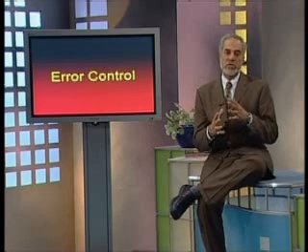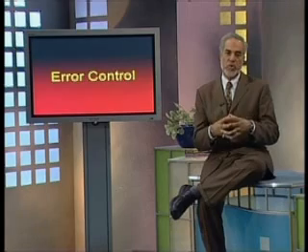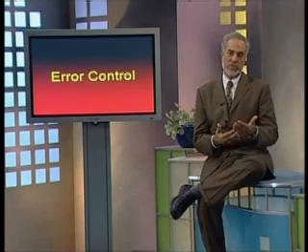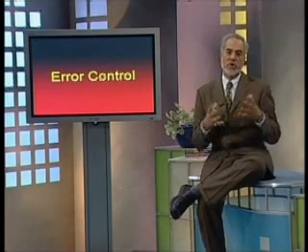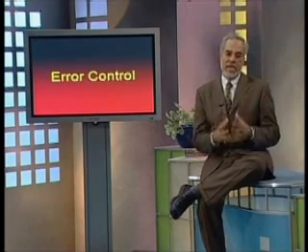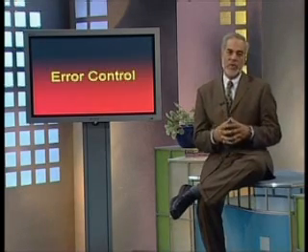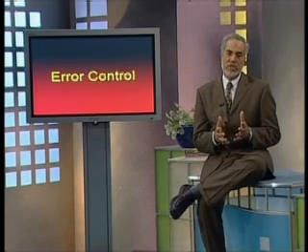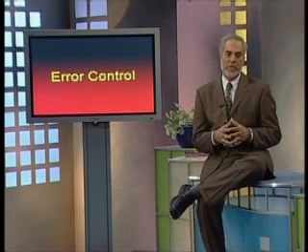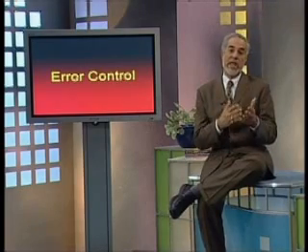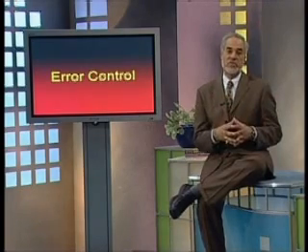We said there are two techniques. In one case, we just find out the error and report it back to the CPU or the controller. The controller can repeat that process and resend that message or resend that block of data where the error occurred. And secondly, it could also correct. However, the correction of errors would require larger overheads. We discussed Hamming code as an example. The simplest was parity code just for detection, then Hamming code, and then the CRC we discussed,